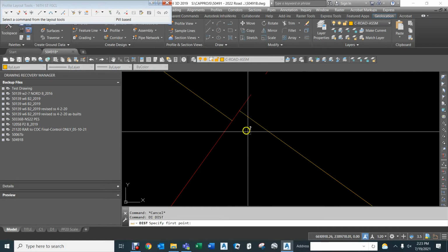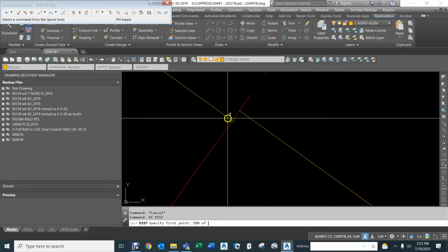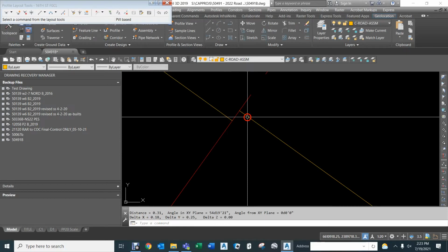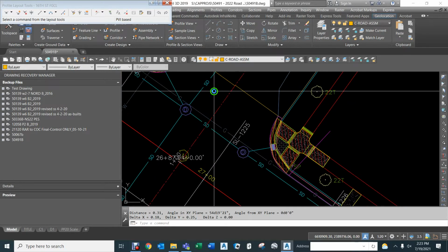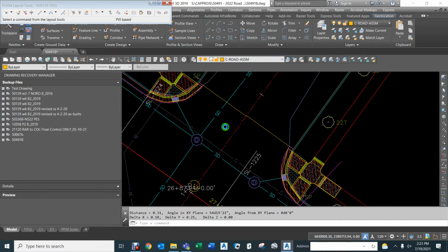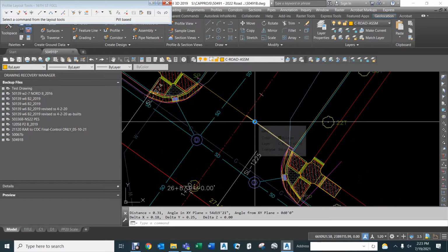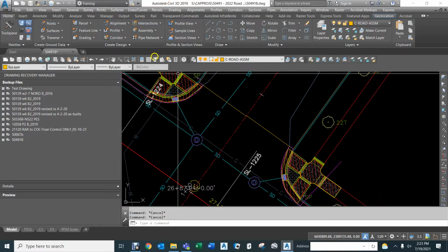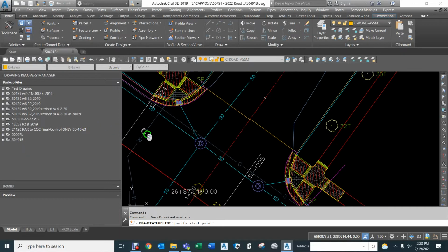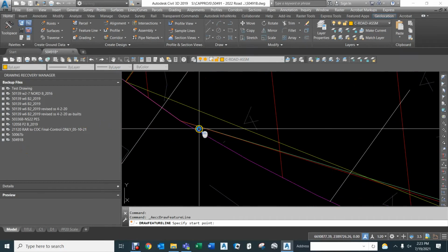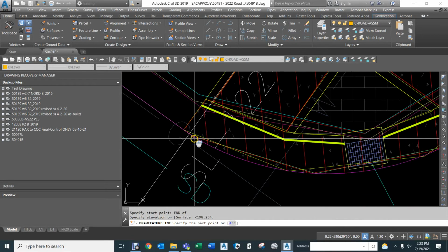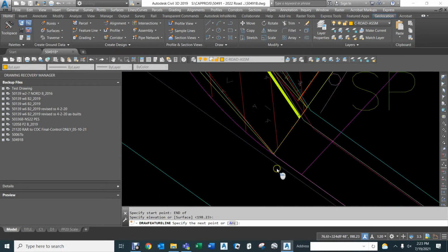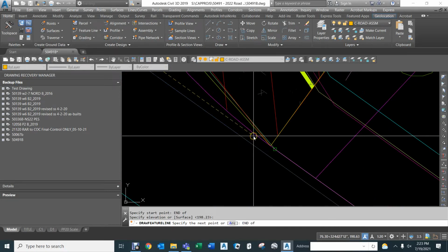So we don't get too excited about that. Yeah, 3100s. So it doesn't really matter because we're just going to take a basic distance and round it to the nearest foot for that. We're going to also do the feature line, temporary feature line, from the end point of this arc, accept its elevation, go down to the end of this arc and accept its elevation.